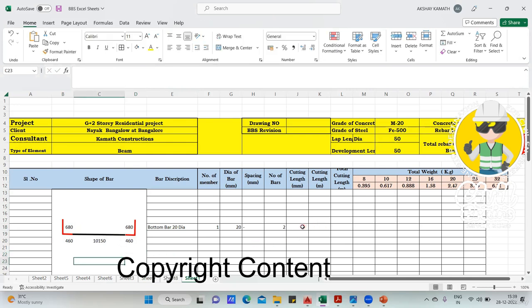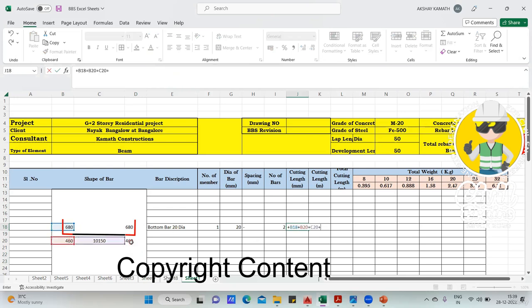Now, how do you do the cutting length? Cutting length will be plus this one plus this one plus this one plus this one plus this one. This will give me the total cutting length, 12430. And since it is more than 12 meters, what we need to do? We need to add one lap length. Now again, 57 times the diameter of the bar is not constant. It depends on the project. But in this project, whatever drawing I'm referring to, they have given 57 times the diameter of the bar. So I've taken it. So the total cutting length will be this value divided by 1000. Finish. And this total cutting length will be this answer.